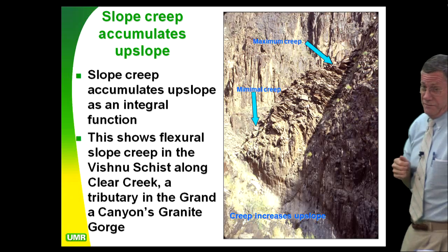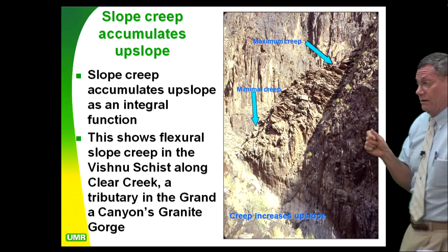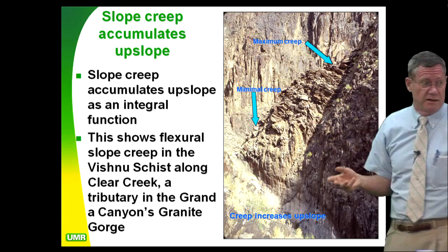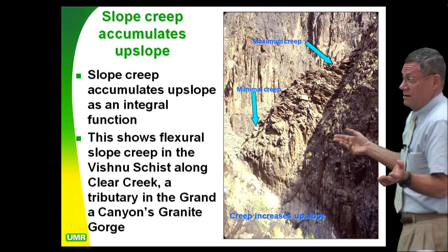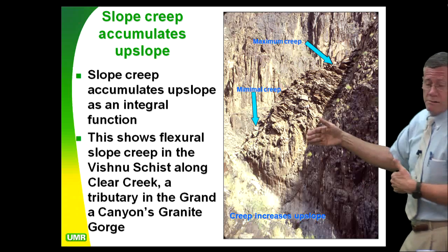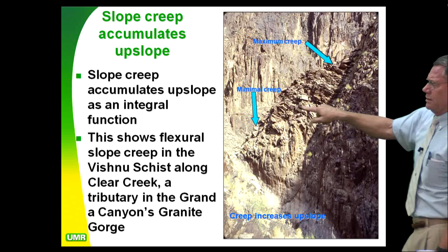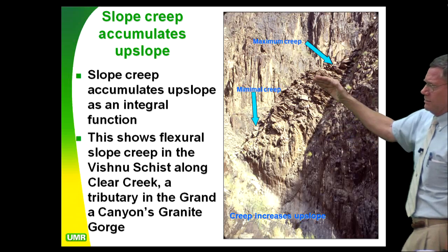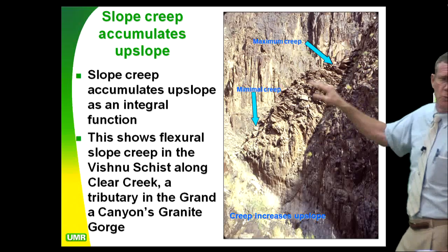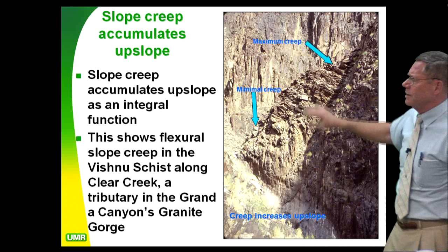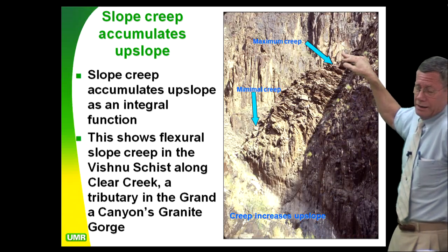And they're experts in this stuff now, because they go out and do a lot more instrumentation than we do, because they don't have a lot of money to spend $1 billion here and $1 billion there on slide repairs. They got so many slides, you can't repair all of them, so you have to decide; it's cheaper for them to move the highway than to repair some monstrous slide. So you're going to have different depths of movement and different amounts of movement, even though it's the same slide feature. And that's how slope creep works as well. So the place I got to be real careful is right up here, because I have the accumulation of all the strain going up the slope.